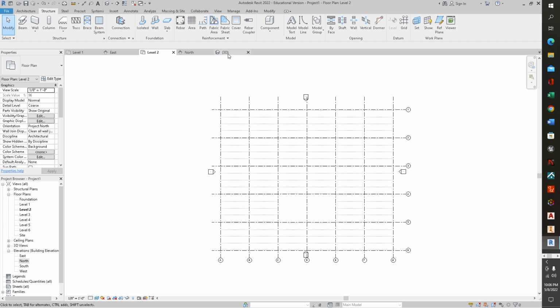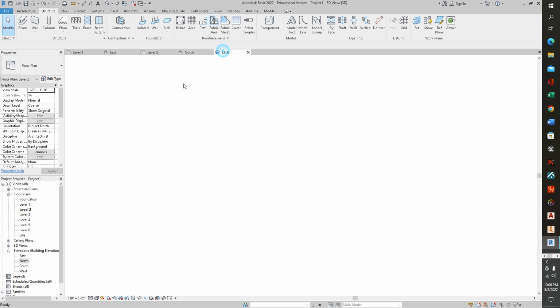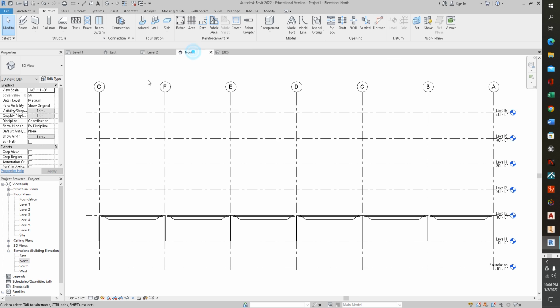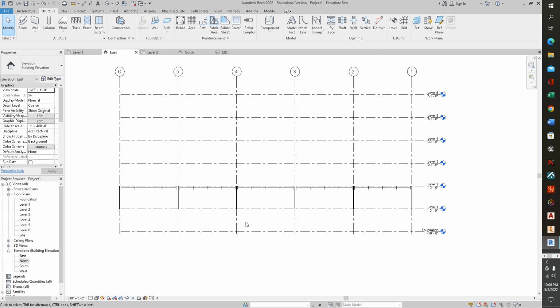And actually what we can do to make sure that we have space for all that, we'll take a look and see what we've done. And we've got 2 open holes there that we can carry all the way back up to the top. And to do that, this is not a bad time to do another bit of fun, easy copy pasting. What we can do is take a look at our north elevation, or any elevation would do. Your east elevation would do fine too. And we can select all of what we put in here and move that on up.